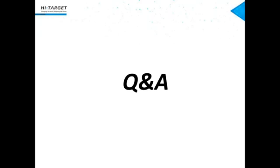If you input plus or minus in SurvCE, it's totally different. For example, if you input minus 100, maybe you should input positive 100 in HighSurv. So it's totally different from SurvCE to HighSurv. Okay, understand. Thank you.